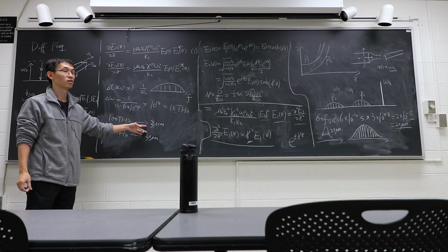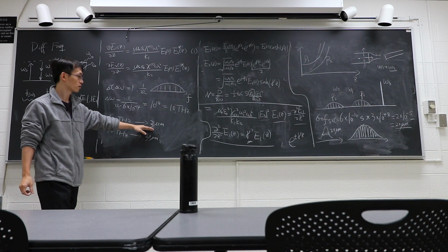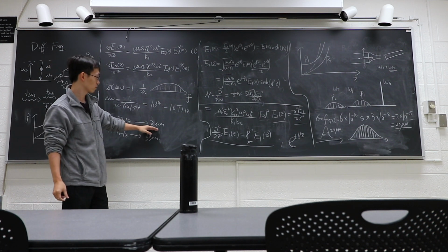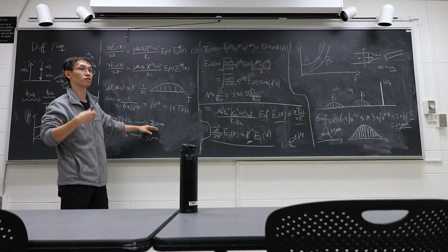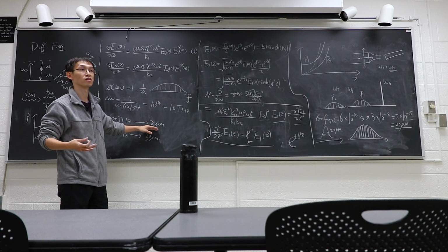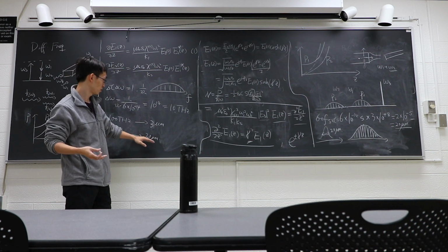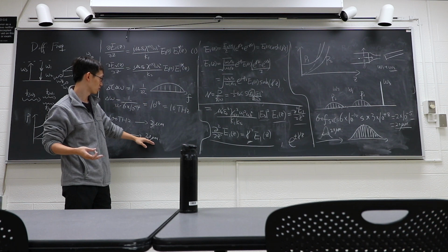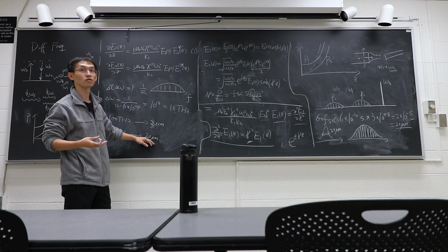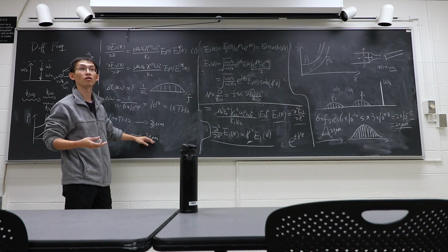And these are very, very different wavelength ranges. For example, for wavelength longer than 3 micron, usually you don't have a very efficient laser diode. You have to use quantum cascade laser. And some quantum cascade lasers have to operate at low temperature, and that's probably a problem.